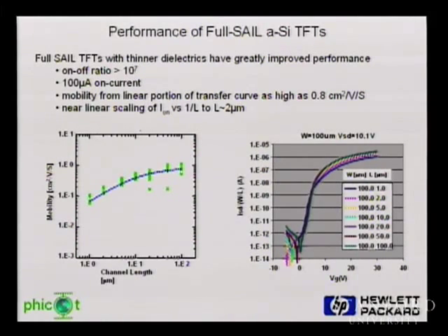And what we were trying to prove with this graphic was that we have the capability to make very high resolution structures. So we can make these amorphous silicon transistors all the way down to 1 micron channel lengths, which, if you know anything about amorphous silicon, isn't easy, because short channel effects set in probably around 5 microns, and so you don't typically get your scaling benefit. The mobility is also affected because the contact resistance tends to dominate as you get to shorter channels. But anyway, these are a pretty good amorphous silicon transistor, as good as anything you're seeing in an LC display today. So in fact, we can make good devices.